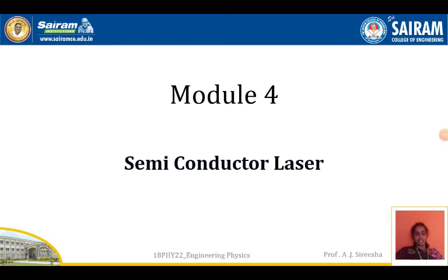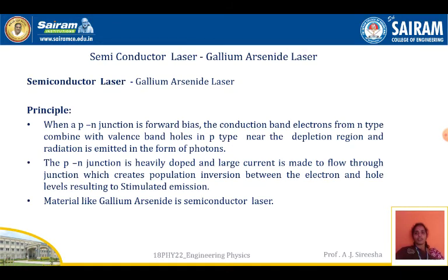In this session, we are going to see the principal construction and working of a semiconductor laser. In a semiconductor laser, the semiconductor used is gallium arsenide. Therefore, it is also called a gallium arsenide laser. What is the principle involved in the semiconductor laser?